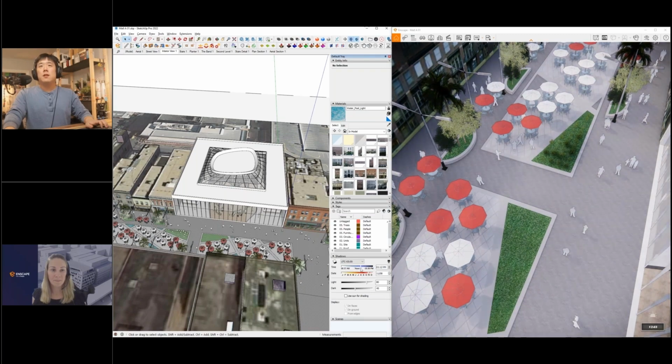And if you want to have a night scene, then I would put it to nighttime and then save the scene. And if you want to change it to afternoon, then have another scene saved with that sun time, or time of the day, sorry, so that you show the shadow correctly. You can do it inside of Enscape by holding down the Shift key and using the right mouse button to scroll left and right like that.